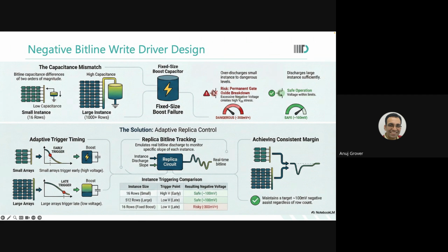If we have a larger capacitance, then what we essentially want is that we will have a certain charge on the bit lines, and when we provide a negative charge, that charge will go to a certain negative value. The voltage of the bit line will go to a negative level. So in that case, if you have a higher capacitance, it will require lesser voltage to configure for that particular charge that you wanted. And then, don't get confused. Always apply the principle of conservation of charge. There are two capacitors, okay?